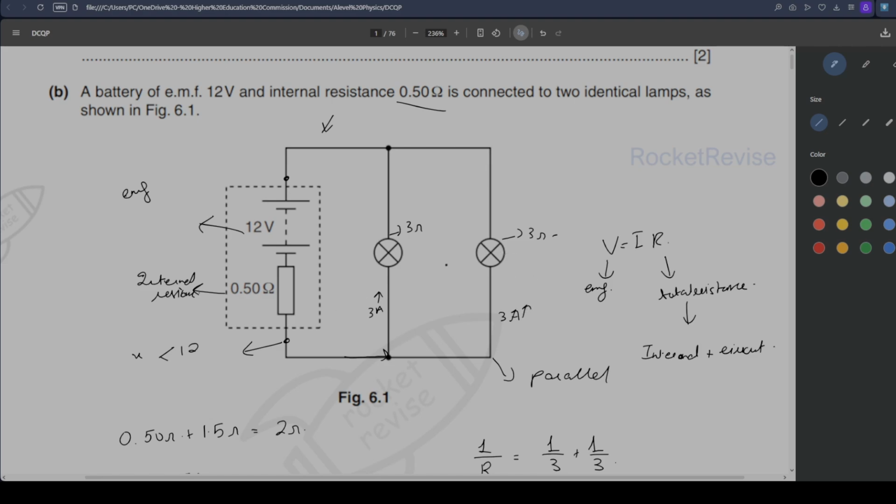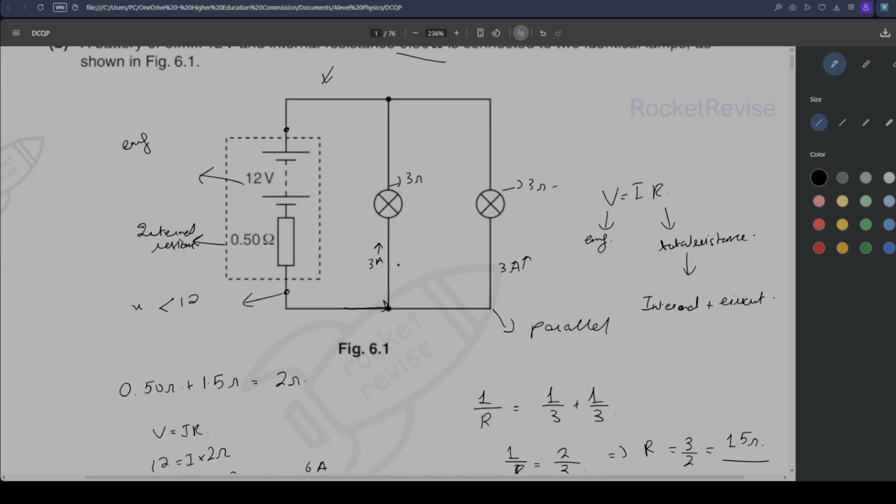If the resistances were different, if you have a parallel circuit where the resistances are different, in that case, your current is gonna be divided differently. It's gonna be divided depending on the resistance values, and the lower resistance is gonna get more current. So just for an example, if this was 2 ohms and this was 5 ohms, more current is gonna pass through the 2 ohm resistor than the 5 ohm resistor. We can just directly write 3 amps because we know that these are identical.